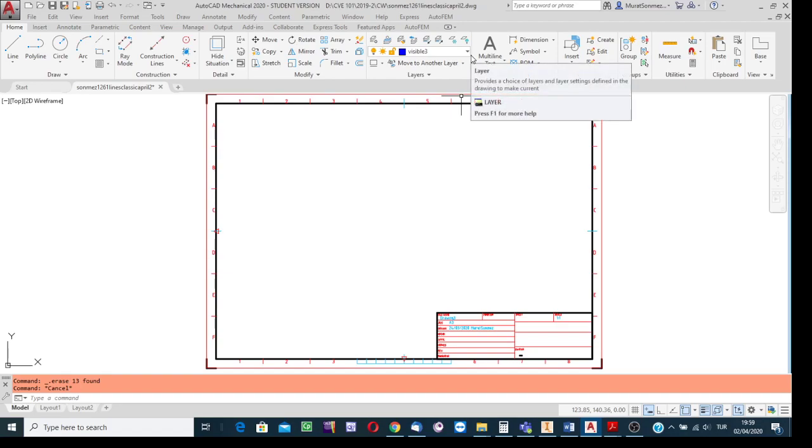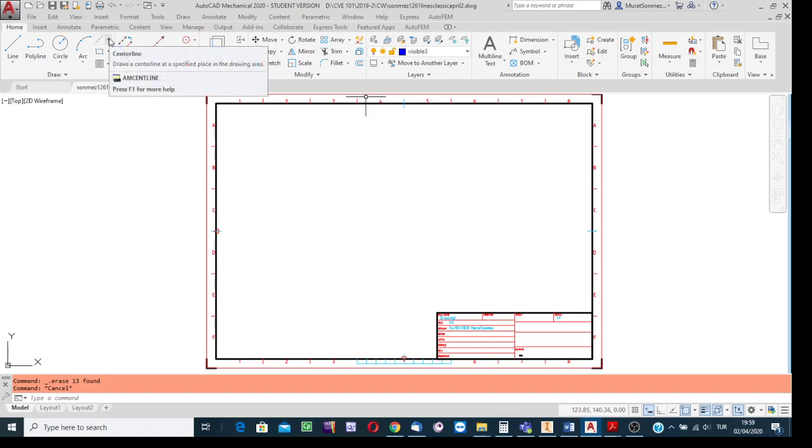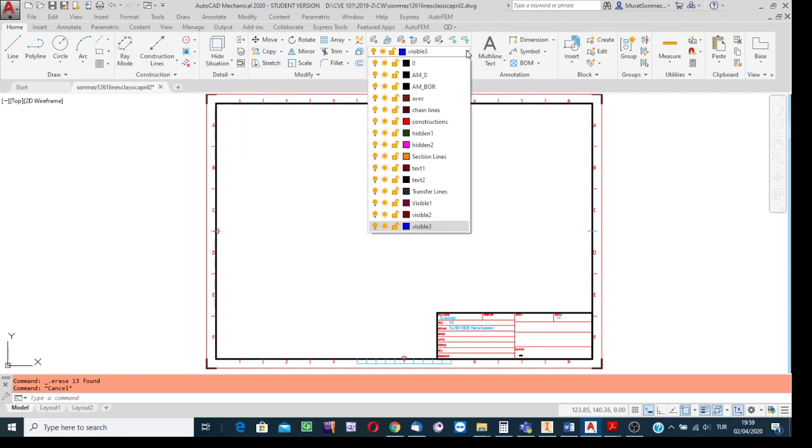Well, first stage, preceding stage, say that you created the circles. How? Demonstrate. Well, it is recommended in the classical method to first create the axes of symmetry and then create the circle. Okay, shall I select the axis layer for creating the symmetry axis?